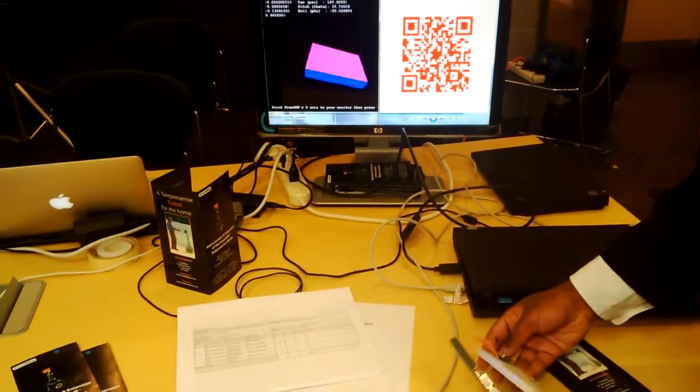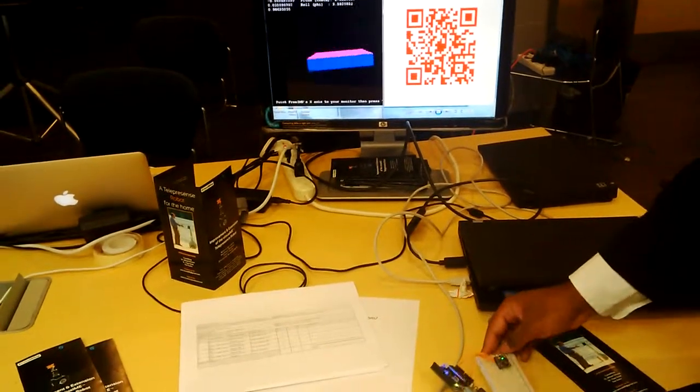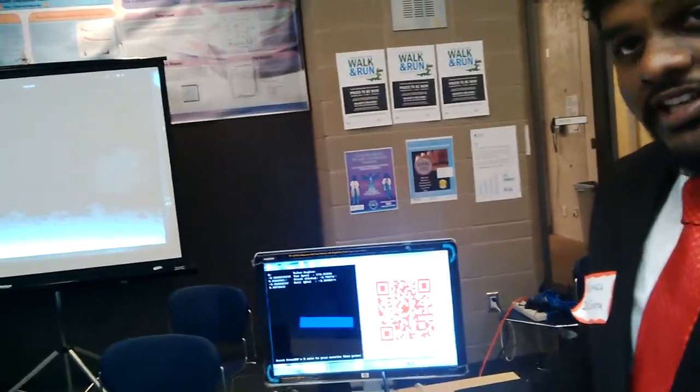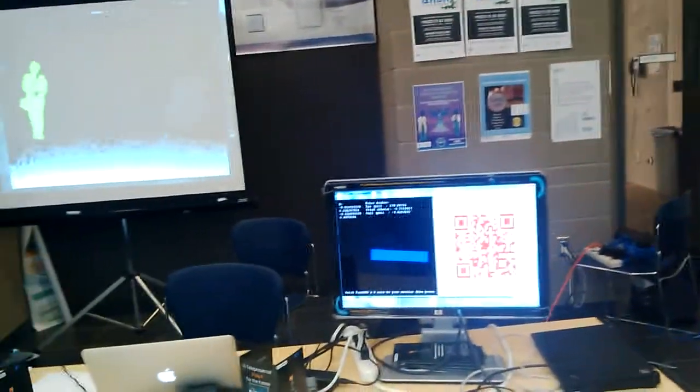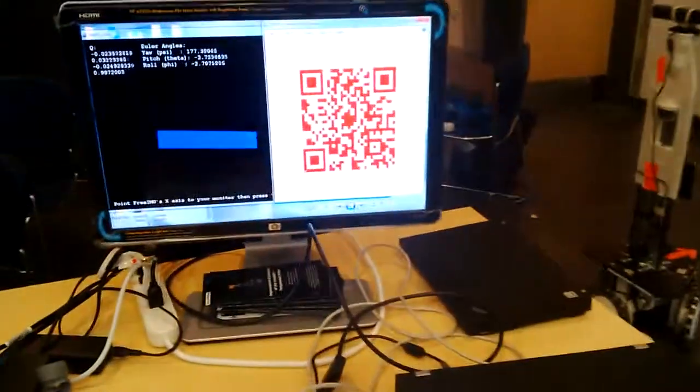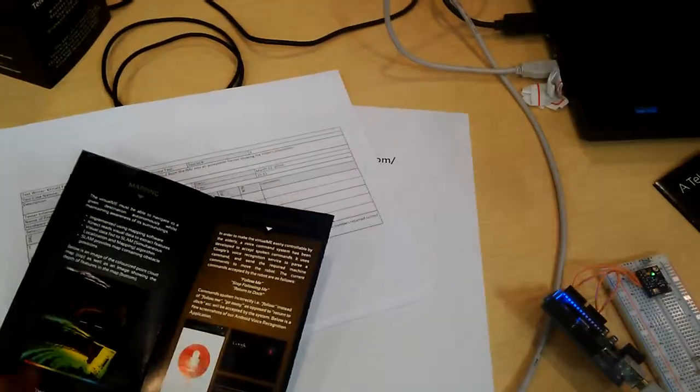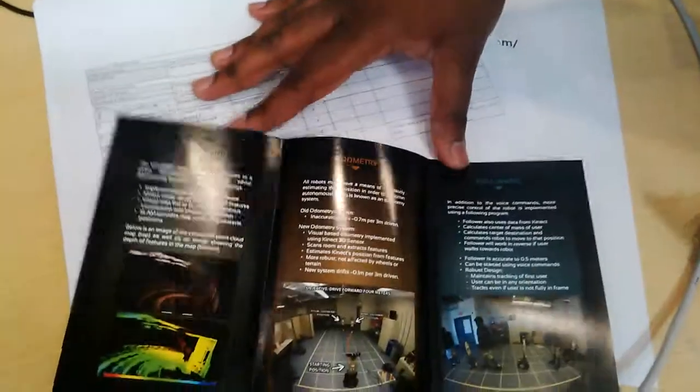This was the sensor which we were planning on using to determine the position of the robot. Unfortunately, we realized that this sensor is only good for obtaining the absolute orientation. When you try to find lateral distance, you have to double integrate the acceleration, and this results in a summing of all the errors over time. So therefore, we moved to the visual odometry system. The visual odometry system basically keeps track of all the features in the room, and it uses these features to determine the position of the robot.